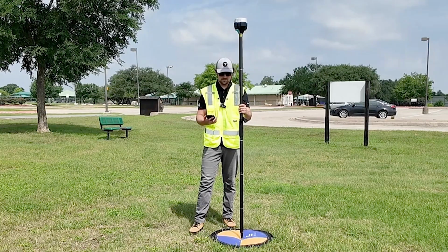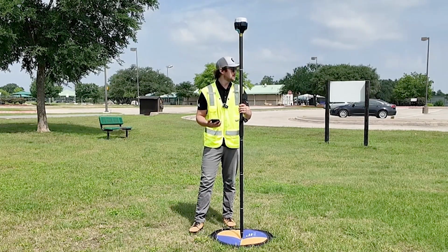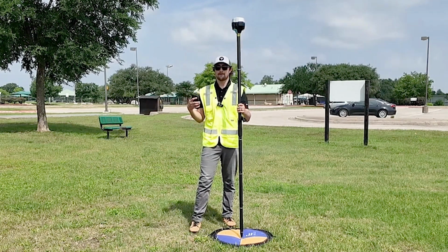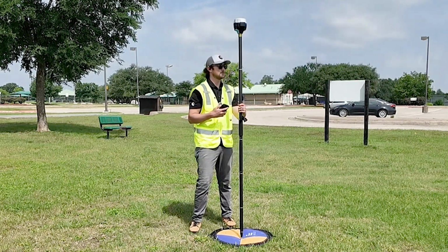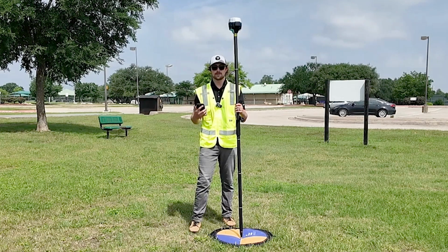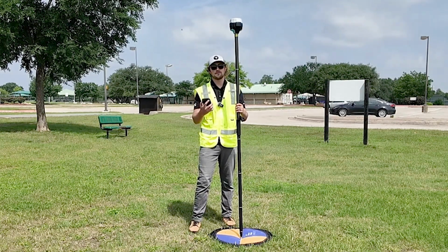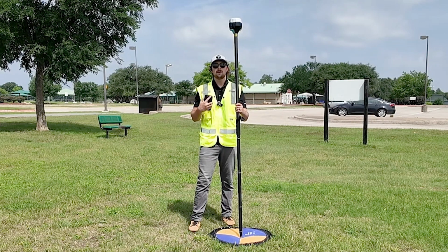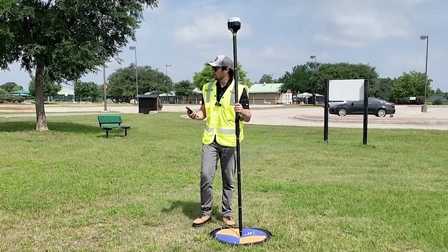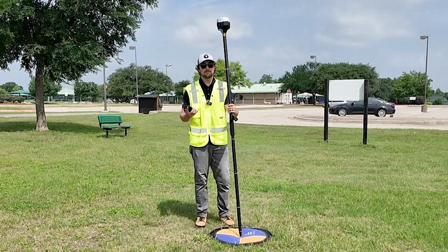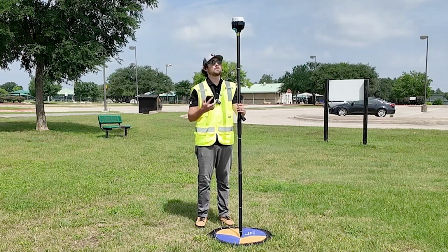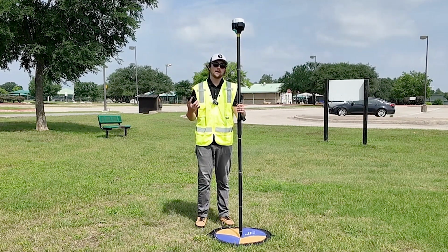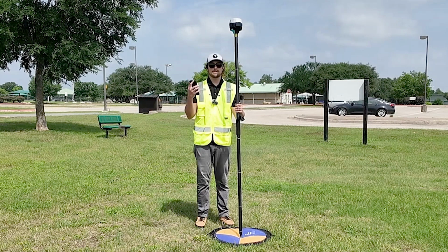All right, so for this point, one of the considerations we had is that we wanted to make sure that when we're setting up these targets, they are 50 feet away from any obstacles, so trees, buildings, things that could obstruct the view from the drone to this target when we're actually doing our mapping mission. So here, we're more than 50 feet away from any obstacle. We're in a clearing here, and we'll have a really good picture of this target from the sky when we do that mapping mission.